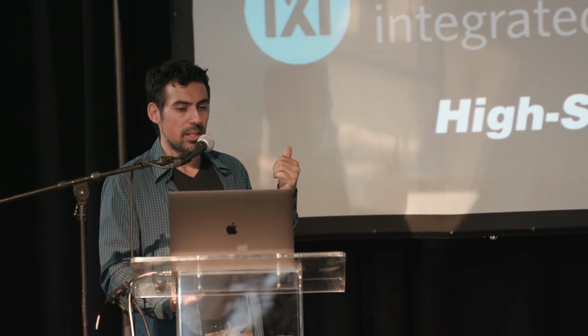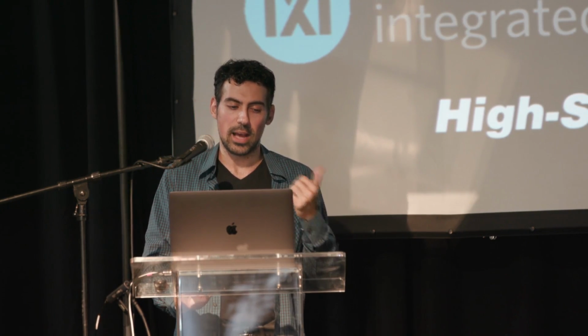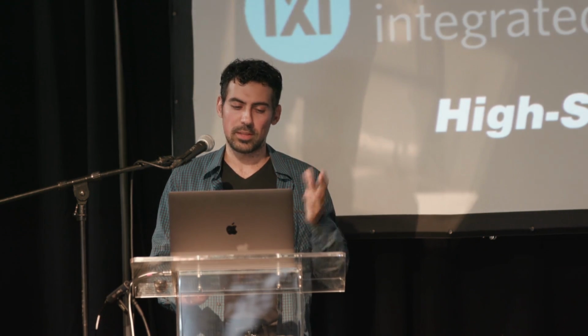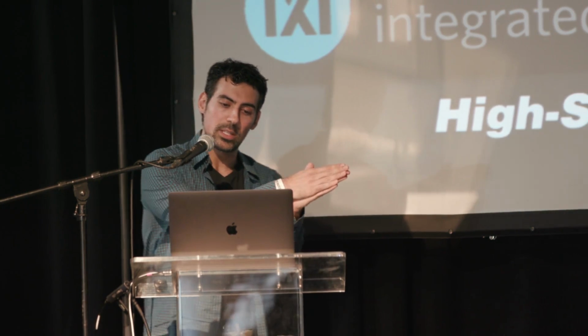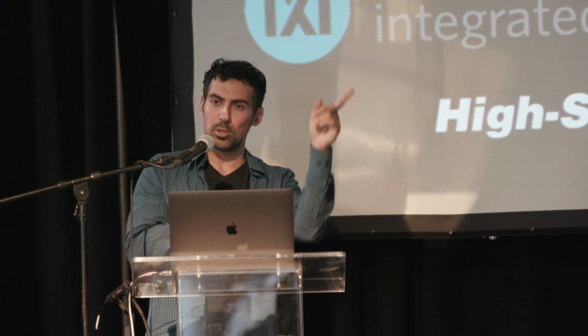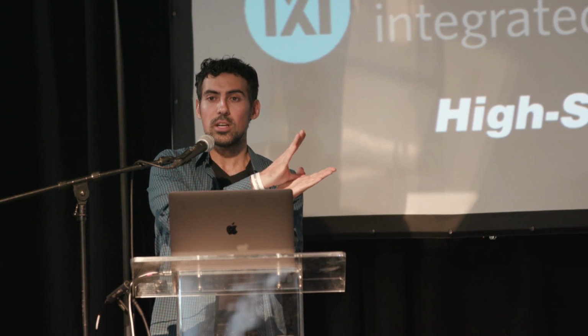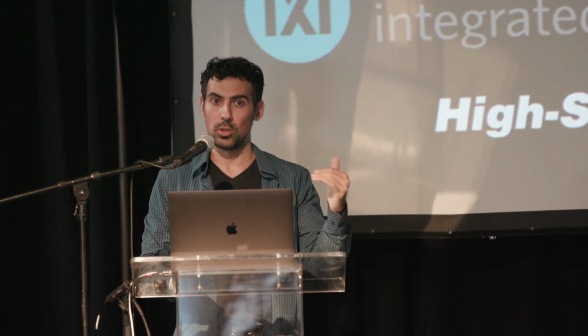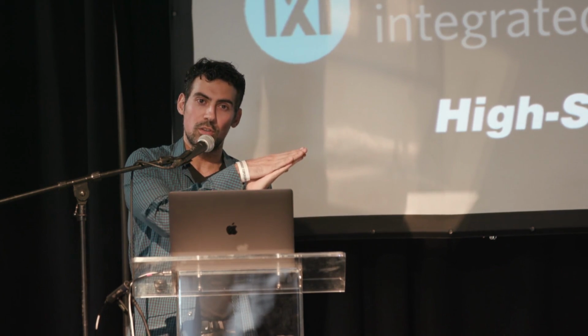However, you don't need to use an FPGA. One thing that you will need for something like this is a fast multiplexer. Chris Gerlinsky found this guy, the MAX4619, which allows something like 10 to 20 nanosecond switching times, which is absolutely incredible when you're talking about muxes. So if you're switching a clock from your normal clock to a different clock, then you can use the mux. Or if you're switching from a voltage, say your normal 3.3 volts or 5 volts, and you want to give 0.2 volts to this device, then you can use this mux. And this will switch for 10 nanoseconds and then switch back. And that will deplete your microcontroller of power, so it skips a specific instruction.